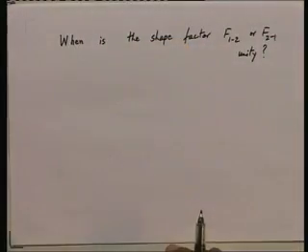And when does this happen? I am talking now of f 1 to 2. It will be unity when the surface 2 completely surrounds 1 and the surface 1 is completely convex.